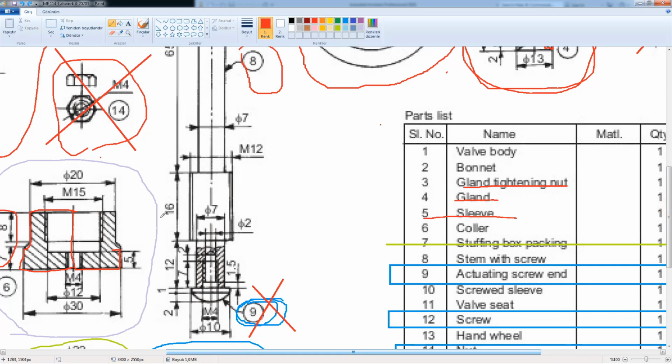I'm going to start with 7mm diameter, starting from this point to this point, which is 12mm, and I will just create a hole with metric 4, with the depth 7mm and 2mm, totally 9mm in hole, and 7mm with the threaded length.